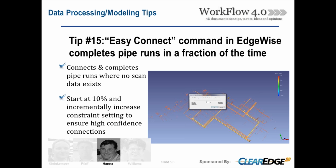Okay. Yeah, that's a great point Larry brings up, and I think it's essential as well that when you do modeling, you preserve the scanner coordinates so that when you're adding more data, everything's coming in at the correct place in the Revit model.